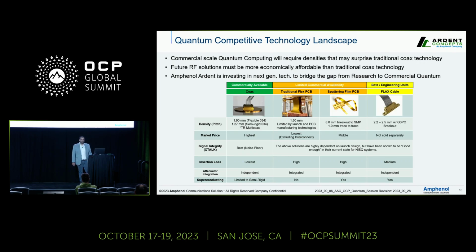This chart illustrates and compares some of the leading transmission line technologies under investigation as suitable mating architectures for the existing solderless compliant compression mount interface. While deploying non-coax-based solutions such as flexible PCBs presents numerous challenges, our investment in cryogenic development infrastructure and our long-standing focus in RF design provides us with optimism that solutions can be realized through time and effort.